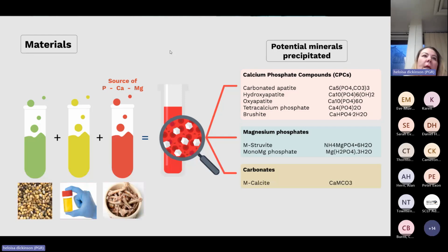And I decided to try to create another method of precipitation, precipitating not only calcite. I wanted to use both byproducts of the hydrolysis of urea. I wanted to be able to immobilize, or in fact use, the ammonium and use the carbonate ions in the crystalline structure of the newly formed minerals. I researched and found out that the best candidate for that would be struvite, which is magnesium ammonium phosphate hexahydrate. And then I decided to try to precipitate calcite and struvite together.